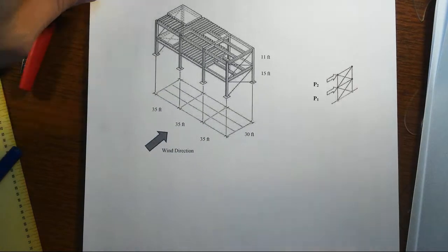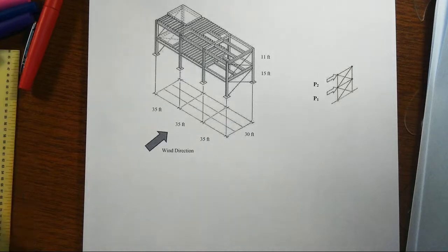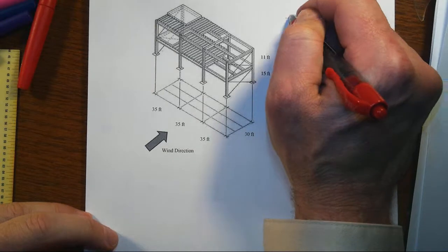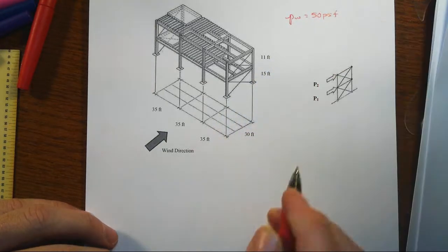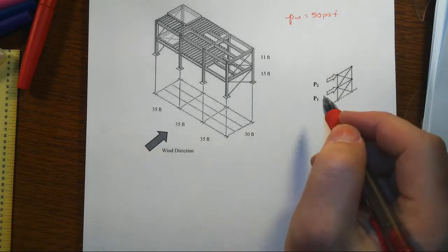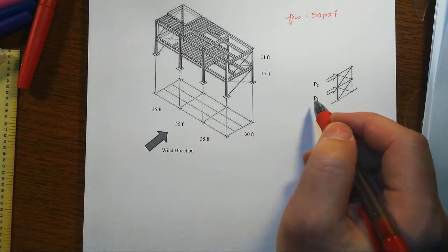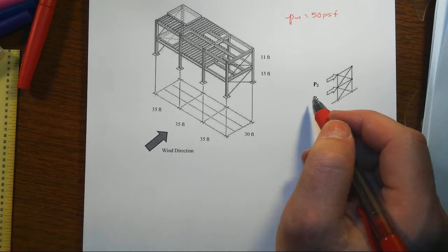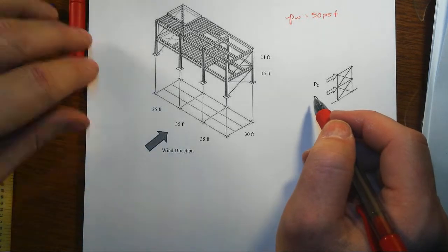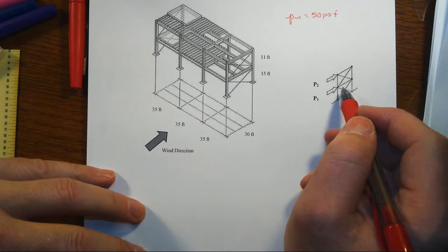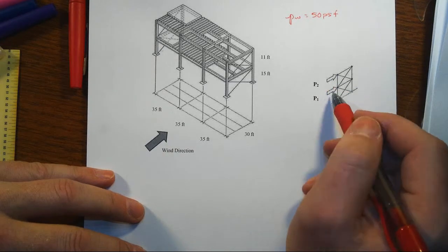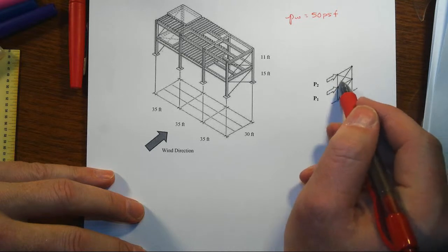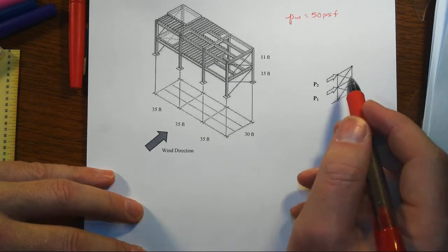In this last and final item on the exam, we have a two-story steel frame structure. We have a lateral wind pressure, P sub W, that is equal to 50 psf, and acts in the broadside direction. Our goal is to find the values of P1 and P2 as that pressure is applied to the external of the building and is transferred over to the diaphragms, and the diaphragms then are connected here at these two levels. So what are the point forces that come into this little vertical X-braced tension counter truss?